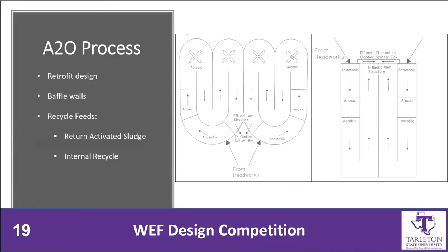To incorporate the A2O process into the plant for each alternative, the oxidation ditches have been sized to prepare for a retrofit during Phase 2, meaning no additional basins are required. This retrofit includes installing baffle walls to the oxidation ditches to create distinct anaerobic, anoxic, and aerobic zones. These existing basins will have supplemental diffused aeration discs installed, while the new basins will have their aerobic zones entirely